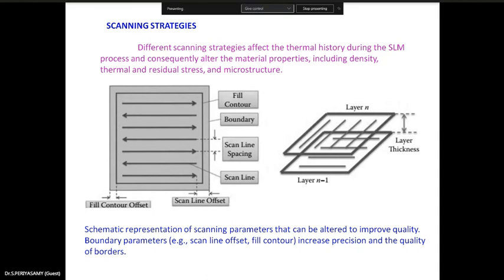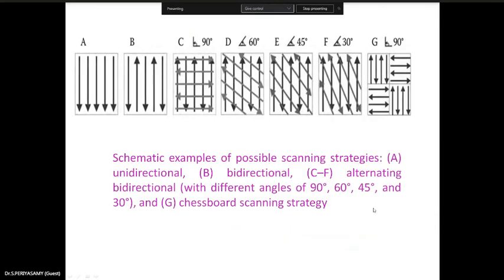So if oxide films or some other layers are formed, they also do not interact with the next melting pool. Even in welding, you can get an oxide layer on the top, even though you are using a flux in the welding rod. Finally, you are chipping and removing that. Any oxide layer that forms also gives problems. So it is very important to avoid oxidation and contamination.